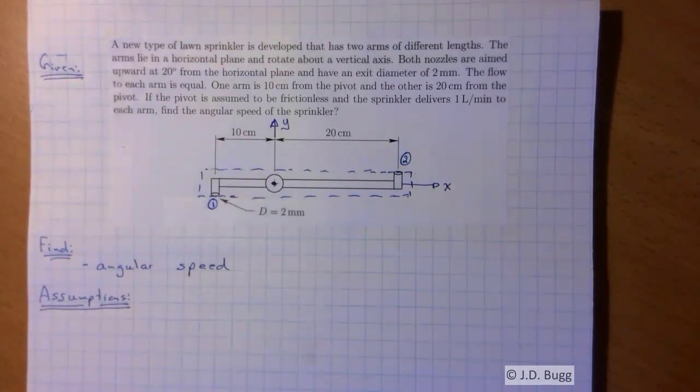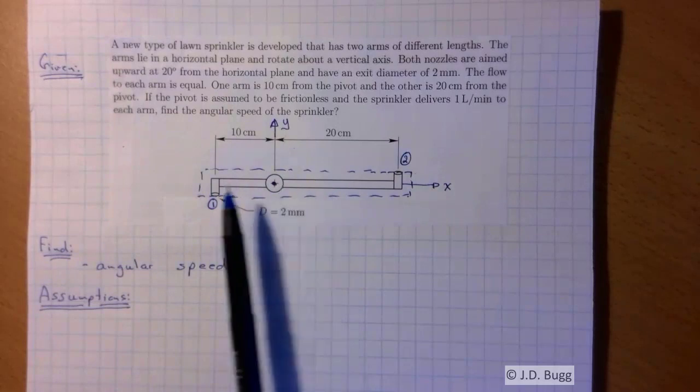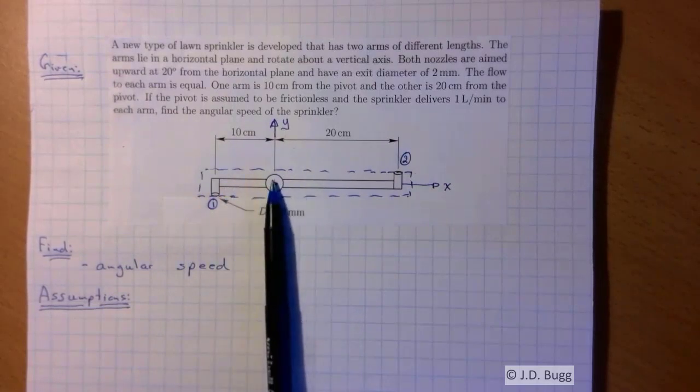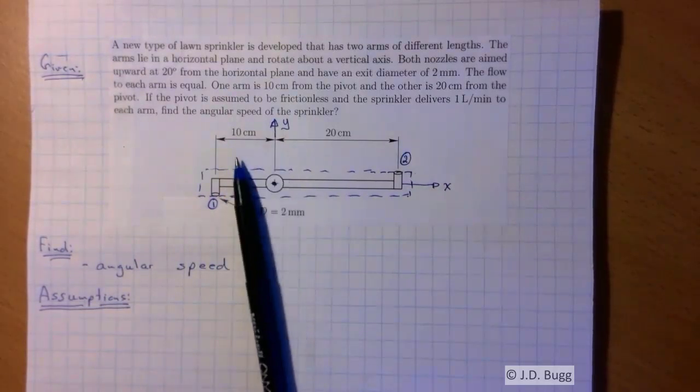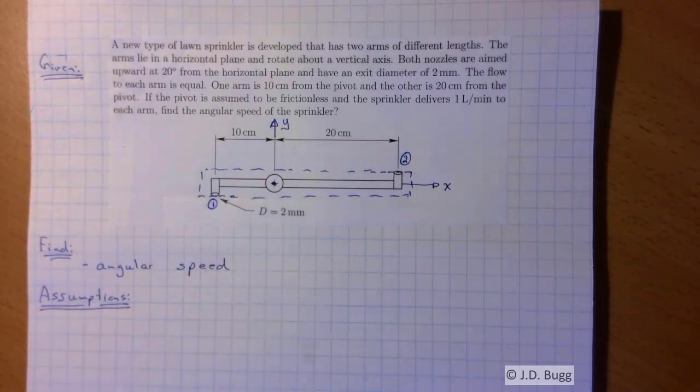So even though our conservation equation has three components, in a little while here, as we work with the equation, the component we're going to be interested in is the k-hat component. We're actually not interested in the j-hat component. So even though there clearly is a torque due to body forces, it's in the j-hat direction, and we're interested in the k-hat direction. So right off the bat here, we're going to neglect the torque due to body forces. So I'll just say we'll neglect body forces.